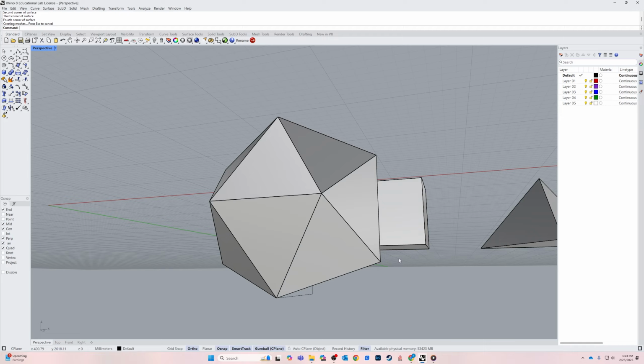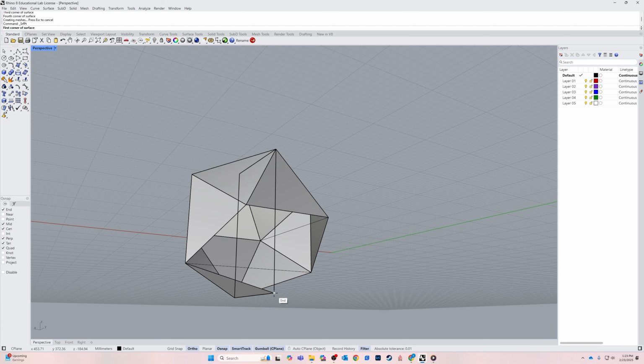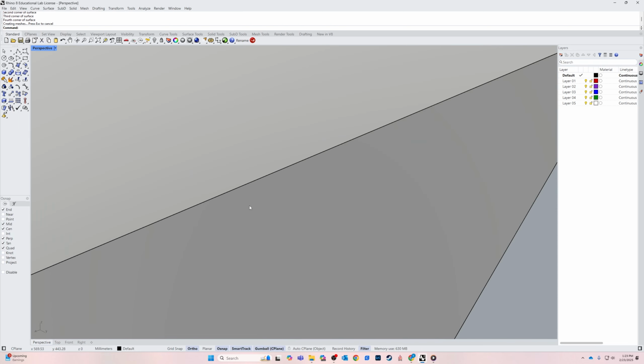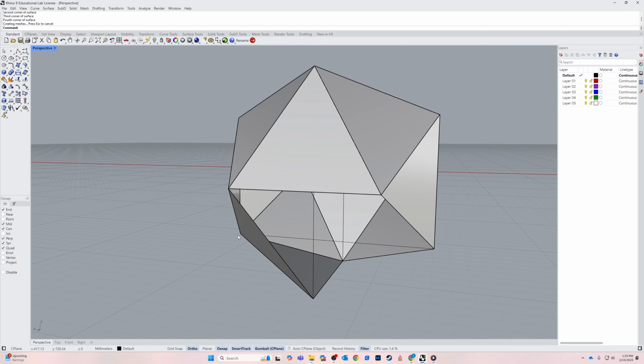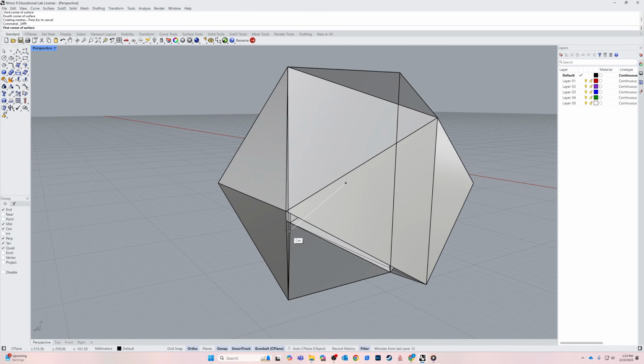So you're just drawing basically the surface right on the corners of where those rectangles meet. And you do need to make sure that they are all perfectly aligned. If there's any gaps or you miss any of those clicks, this thing ain't going to work. So you might have to start over if something goes wrong like that, but it's all good practice. So just making sure you're getting your end snaps.